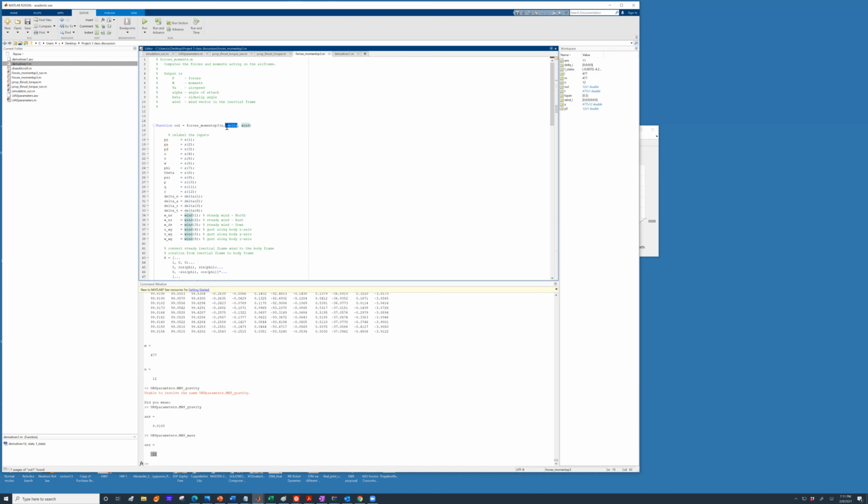Delta values are the values of the control parameter. And if you look at what it's going to do, it's going to grab the value of x and map it to Pn, Pe, Pd, U, V, W, phi, theta, psi, P, Q, R. And then I want you to note delta E, delta A, delta R, and delta T are all the delta.